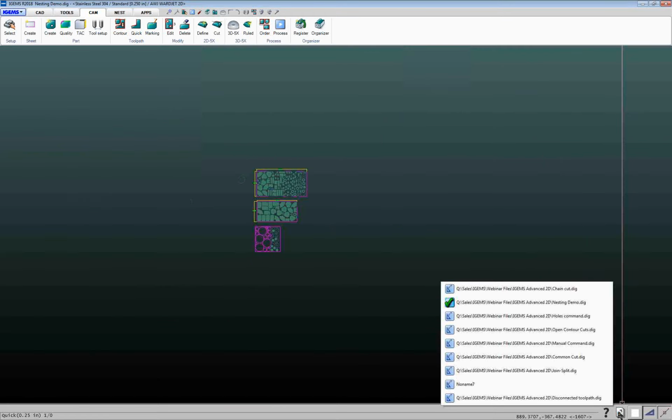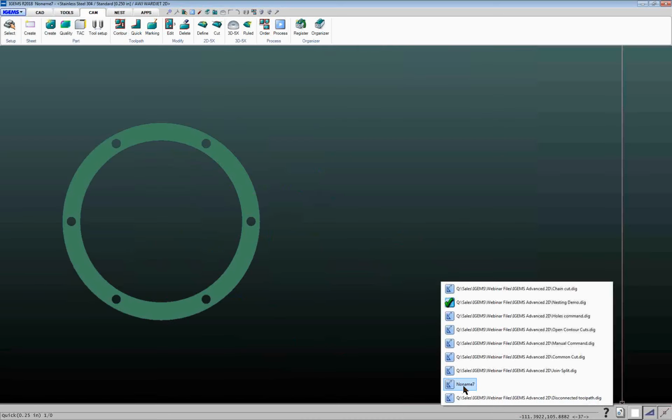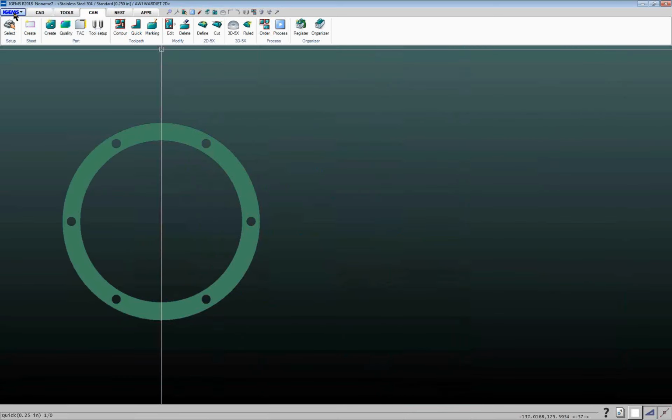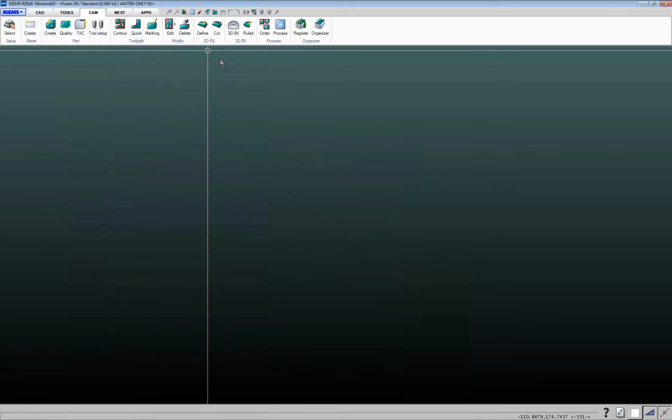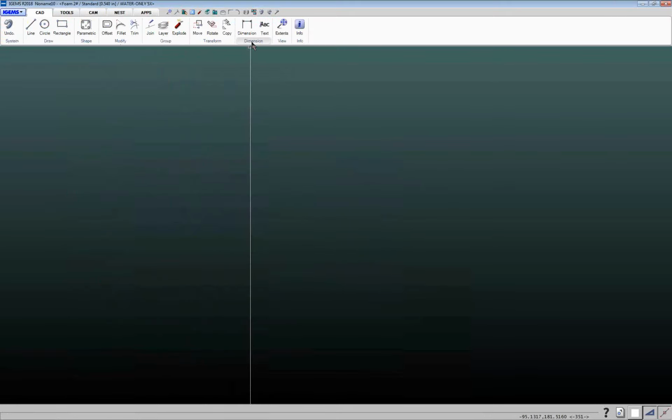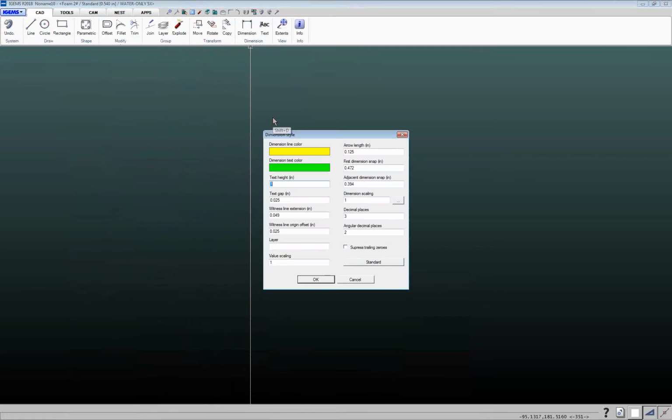And let's see, show you here. I talked about this one last time, but just wanted to review this one because it can be helpful. It's if you do want to create a template. So if I do a new workspace, again, normally, like when you first install IGEMS, you go into dimension styles. Normally, things like decimal places will be set to 2, and text height and things like that might not be how you want them to be.